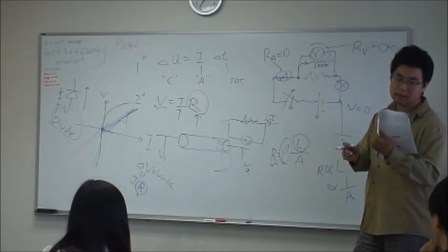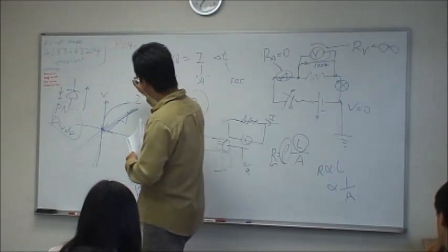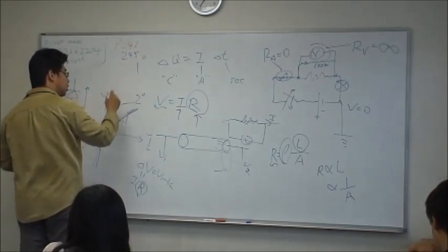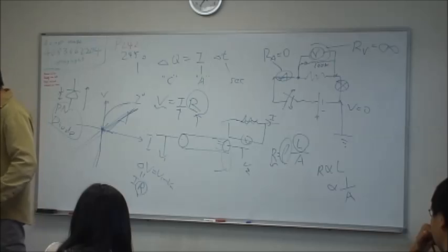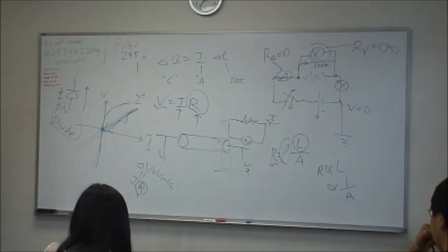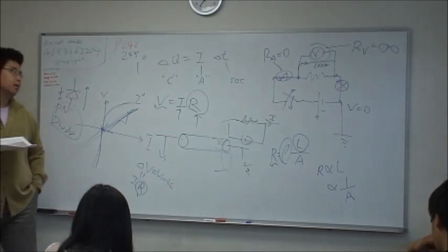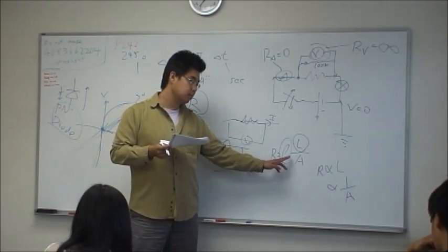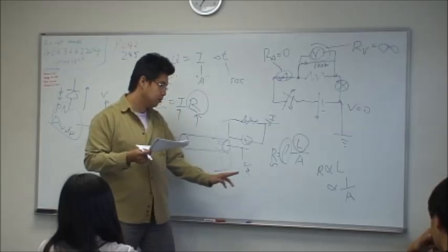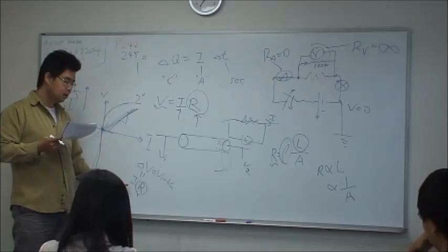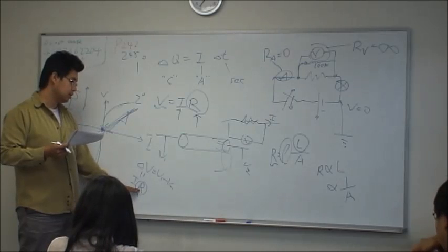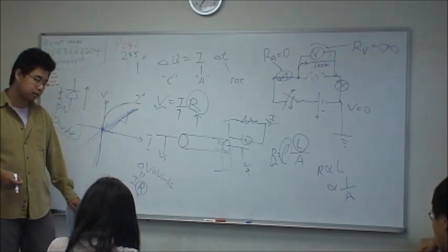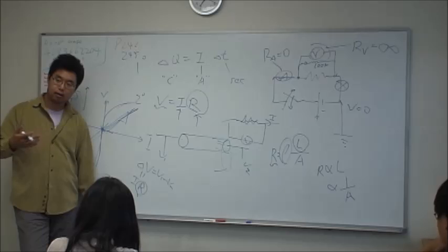If you flip the page, on page 045, there is a resistivity for different materials. What you can see here, everything is quite a small number, 10 to the minus 8, other than carbon, 10 to the minus 5. So rho is very small, 10 to the minus 8, which means R is small, which means you can pass through a high current, like 100 amp of current, with this kind of very small resistance, and the voltage drop is really small. That's what we use at home.